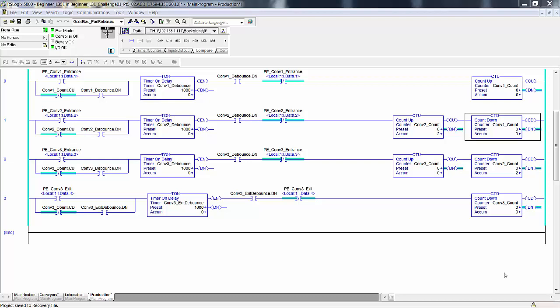We all understand this. At this point, you write a program to control the process by what you can sense, see, with the sensors, and what you can move with the actuators, not to mention capturing production data with your program. You look at your sensors and your actuators, and you write a program to take the data from the sensors through some logical sequence to operate the actuators. You haven't actually seen the machine yet. You have a functional specification. We'll just let you have a drawing set at this point. You really don't need a drawing set at this point, but we'll just say you have a drawing set at this point so you can actually alias some I/O.